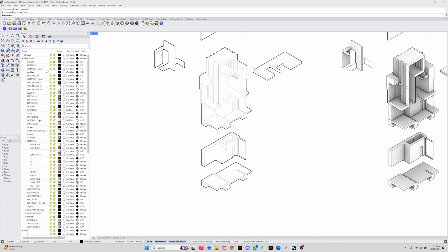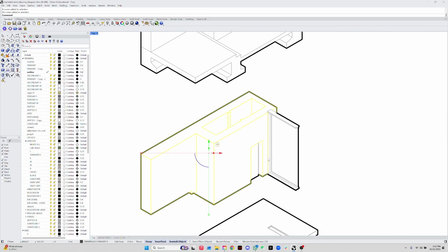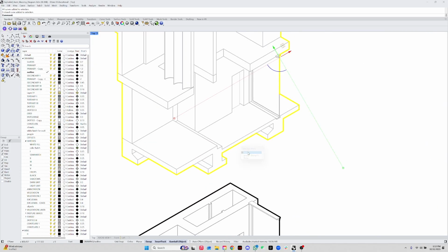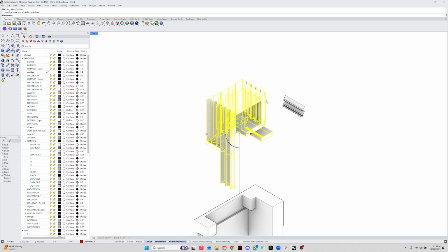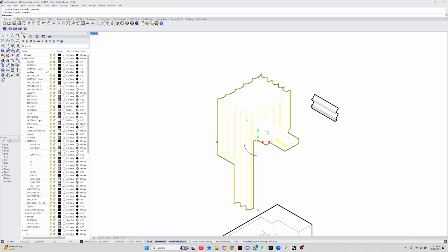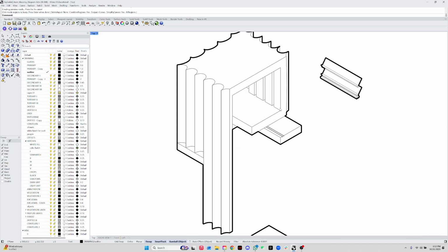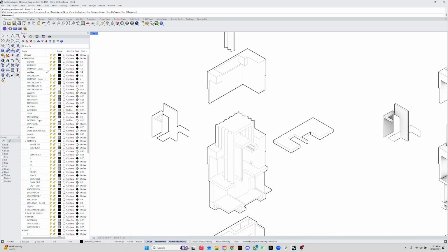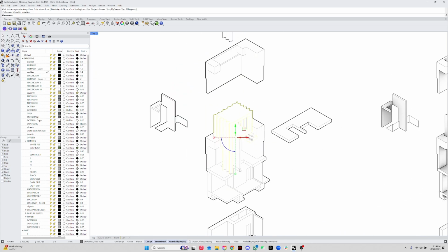Right after that, you do your line weights and you are sure that everything looks okay and everything looks good. Then after that, you're going to do your outer boundaries, right? But for example, let's say that you're not getting your mesh outline, it doesn't work. Just go to your cleaned up geometry, click your group, and just do curve boolean. I mean, that's your second way around. And then just click outside, you get a new curve. Okay. So just make sure that you clean your stuff, so when you do your curve boolean, everything is a closed curve.